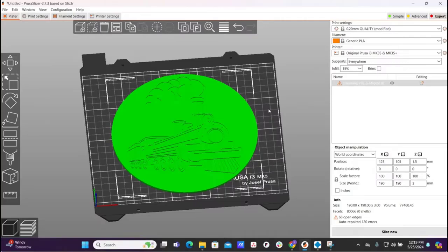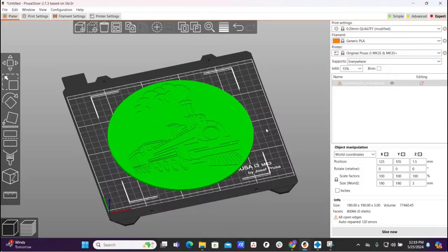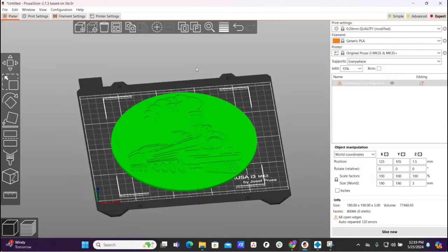If you want to do it a little thinner, if you have a lot of curved objects like the file that I'll pull in a second, you might want to do it a little thinner or do something called adaptive, and we'll touch on that in a second. But if it's a very simple, flat piece with 2 colors, and I just want to make a coin shape like this, what I would end up doing is, 1, verify quality, 0.2 works. Infill, 0.15 works for just about everything.